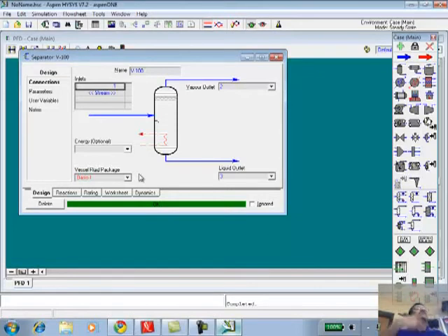So you put a loop around the solver and say, I know only temperature, so I'm going to give you a guess of temperature, and you predict me the propane composition. I will compare it against that. And if the difference between what I predict and what I want is not 0, then I will predict the next value of temperature guess using the bisection method or the secant method. So I can now iterate on that because computers are very good at this trial and error. I don't want to test 100 temperatures myself, but I can let the computer do it by putting a loop around it. That is how you would do it in MATLAB.